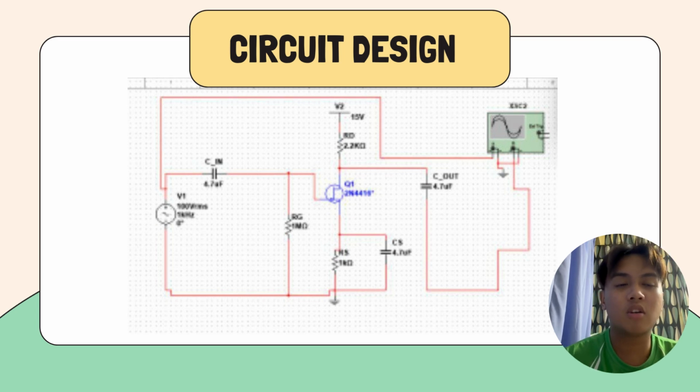To summarize the design goals, by using exact values, a 15V supply, a 2.2 kilo ohm drain and a 1 kilo ohm source, we have designed a stable amplifier that is ready for simulation and comparison against our theoretical results.